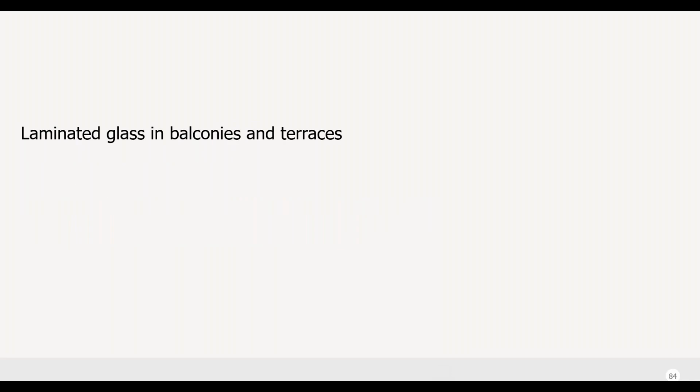There's been much discussion in the industry of the use of laminated glass in relation to its performance in fire. Laminated glass is quite often used as balustrading, as it offers many advantages, such as allowing daylight and views through, giving protection against wind, and also provides an imperforate balustrade to access decks in accordance with BS 9991.